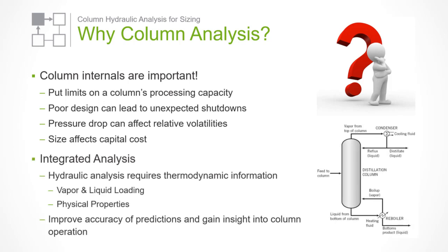Doing column sizing with integrated analysis in Aspen Plus is necessary because thermodynamic information such as vapor and liquid loading and physical properties is required for hydraulic analysis. With this integrated analysis, the designer can improve the accuracy of predictions while gaining insight into column operation.